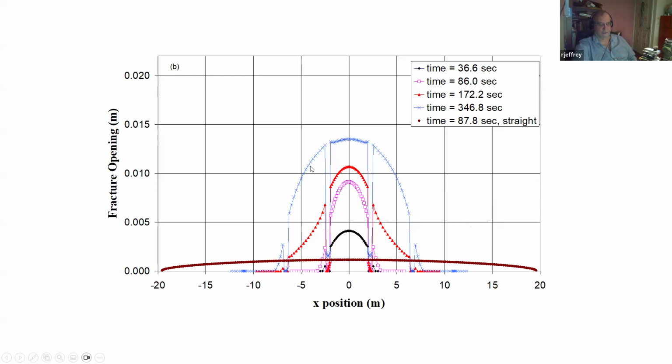The interesting thing is the fracture was still high pressure at the center because of these restrictions. For example, at the second set of offsets, but the first offset had opened to actually be wider than the straight fracture at that point. So essentially, it was no longer offering a pressure restriction. It still had a width restriction there, but not sufficient to produce any pressure drop. So that's the story, basically.